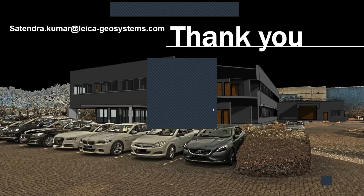Yes. There are various ways to georeference the data. One way is if you have your own controls installed, we can reference that data in the software based on that. Or you can mount a GPS receiver, like your GPS rover, on top of the scanner in the P series, and then take the geo coordinates. The third way is to go with a GPS rover and put one scan on a known geo-coordinated position, and later it can automatically merge all the point clouds and make it georeferenced data.